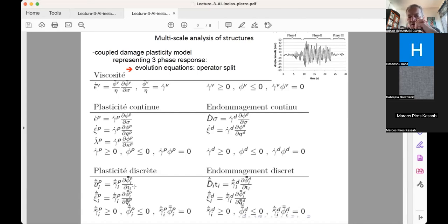And what was really the goal? The goal of our work was to be able to replace the interpretation of damping and go away from something called Rayleigh damping, which is typical of many simplified analyses in dynamics. Rayleigh damping is a choice of the damping matrix. First of all, damping phenomena is related to the rate of deformation. And basically, you have a damping matrix, which in Rayleigh damping is restricted to be a linear combination of the mass and stiffness matrix.